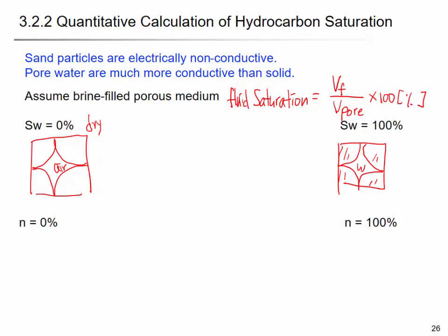So if the pore, which is the space except the sand is occupying, is filled by water 100%, then it's 100% water saturation. If it's filled by air or the gas, if it's dry, then it's 0% water saturation. Okay. From here to here, maybe we may have some intermediate stage with some water, right? Maybe some water here.